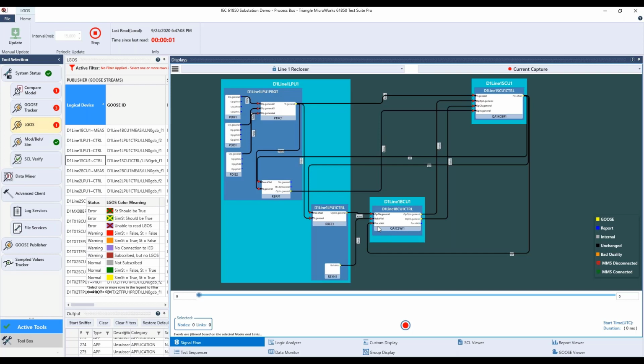It typically needs to know the position, but it also goes to the switch control, the CSWI. The trip from the protection also goes to the breaker failure, and it also goes to the recloser to initiate those functions. And then from the recloser, we have an op close. In our design here, we have decided we do the reclose through the switch controller in order to make a reclose with synchro check. That's where we get the synchro check information in.